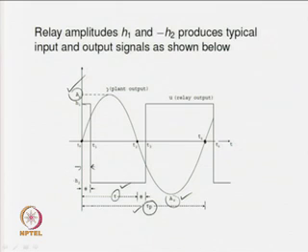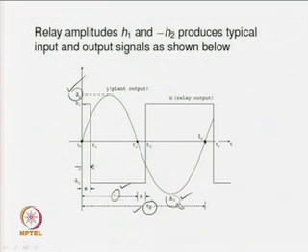So, these are 4 distinct parameters, measurements one can obtain from the output signal. What benefit do we get from making more measurements? It is possible to estimate more unknowns associated with the transfer function model. So, more measurements, more equations, more unknowns can be estimated.